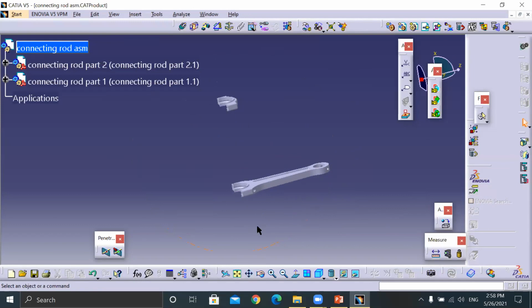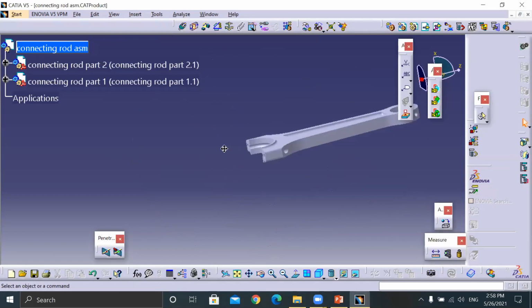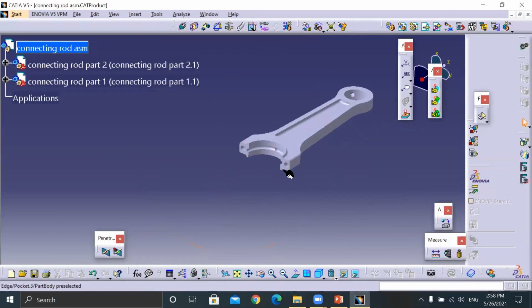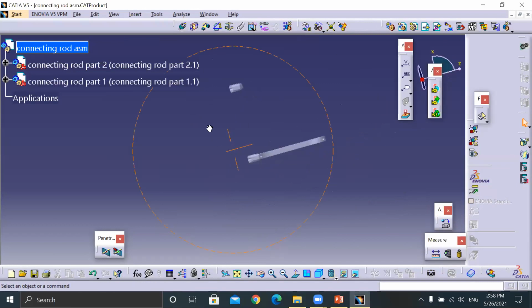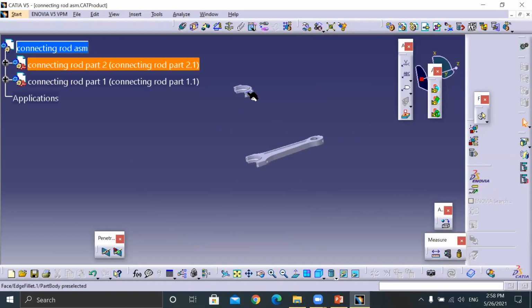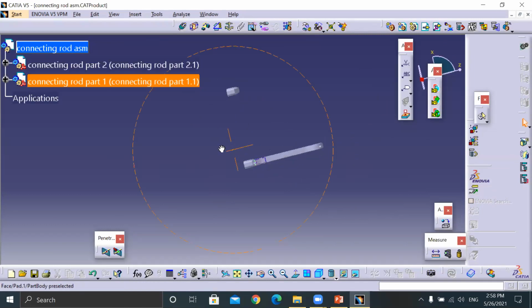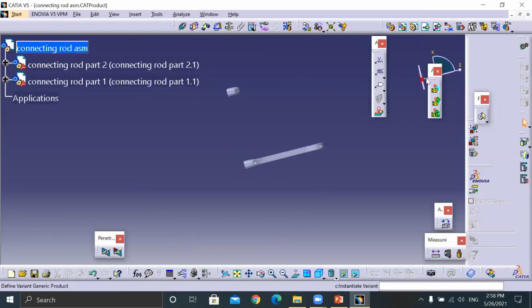Look, contact constraints. No, no, rotate contact and align with the connecting rod. Yeah, align with this hole. Okay, look, this one is like this. But you need it in the other direction. So for this, you need rotation of exactly 180 degrees. Okay. So look, which one is exactly in the middle? X-axis.